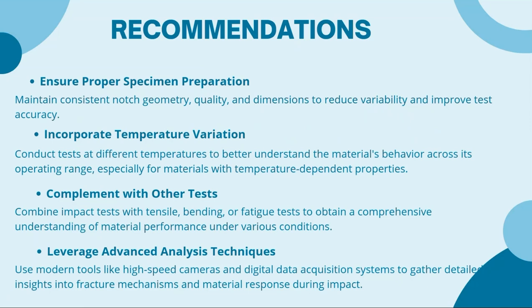You can conduct tests at different temperatures to better understand the material's behavior across its operating range, especially for materials with temperature-dependent properties. Next one is to complement with other tests, where we can combine impact tests with tensile, bending, or fatigue tests to obtain a comprehensive understanding of material performance under various conditions.